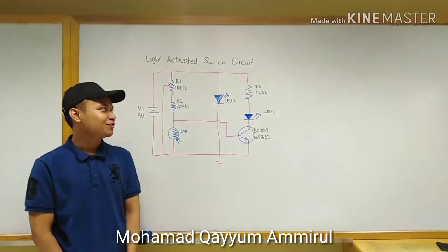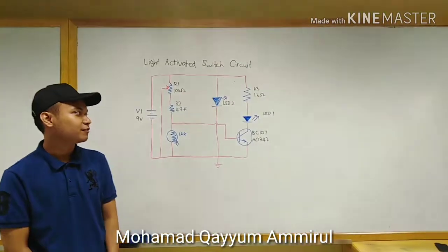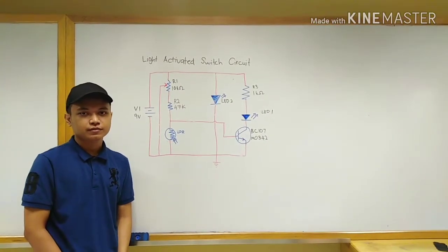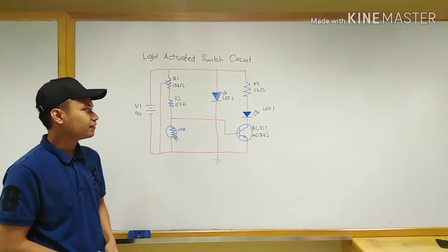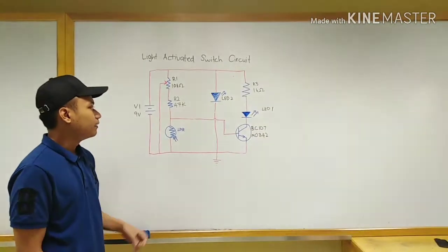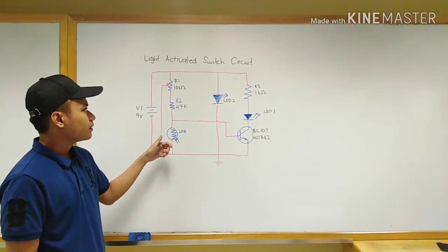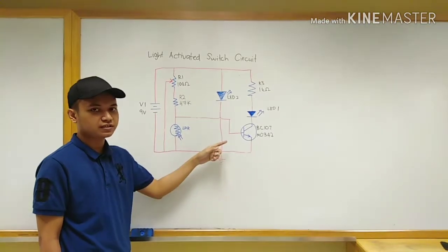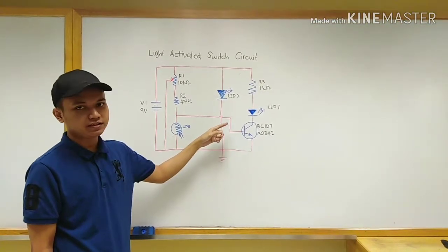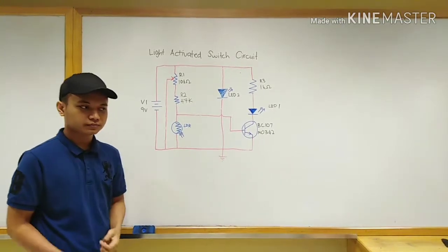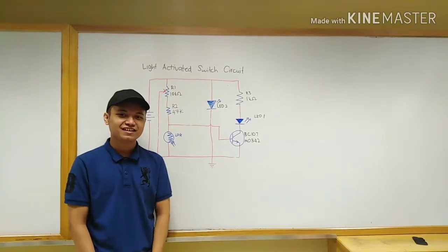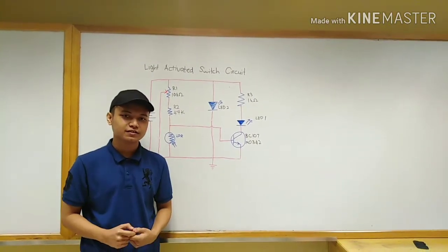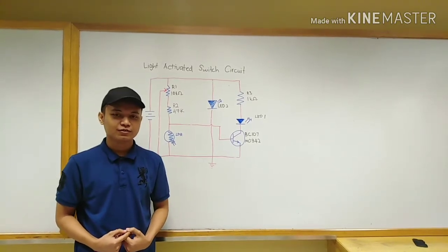Hi, I'm Koyu. Today I will talk about our conclusion for this project. In this project, we basically inverted the function of the LDR. From this circuit, when the LDR is blocked, the current will choose the lowest resistance path to the base of the transistor, and it will light up the LED. Also, the LDR has its highest value in darkness, and as the intensity of light on the resistor increases, the value is reduced. That's all from us. Thank you.